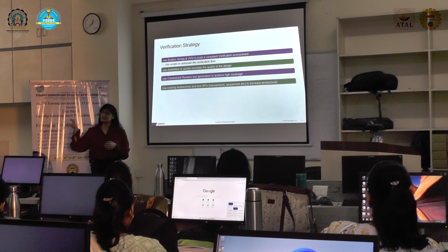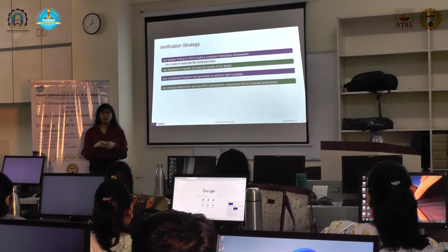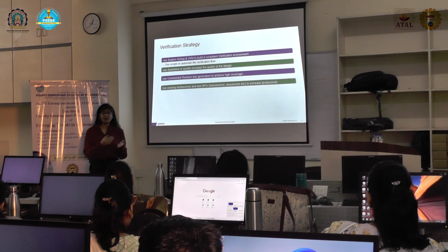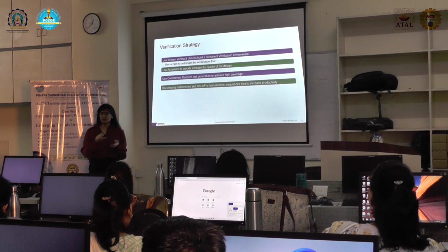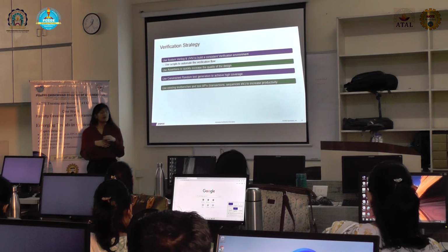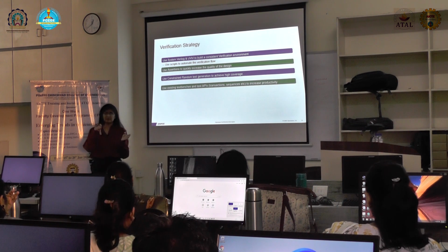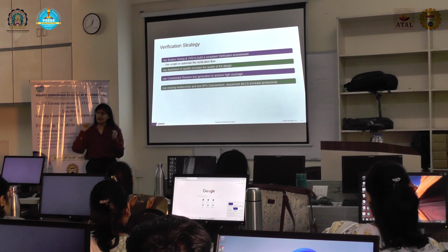Let's say we have register space. We want to write data and collect data from that. Now, in Verilog, what we have to do is write code which will specify that the address line is this and collect the data on this particular line. For SystemVerilog, what we do is we create an interface. We have a variable which will point to the address and data.